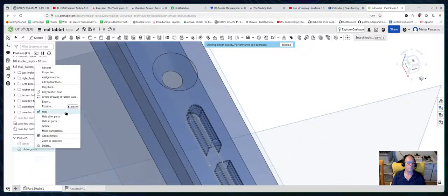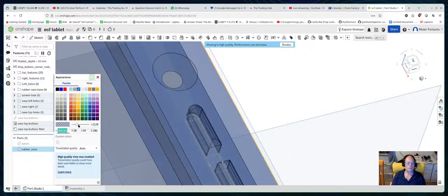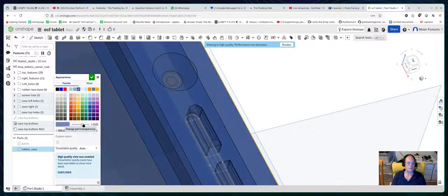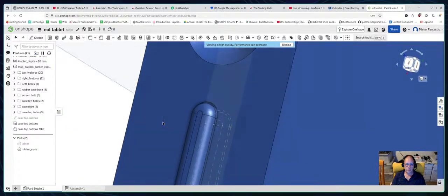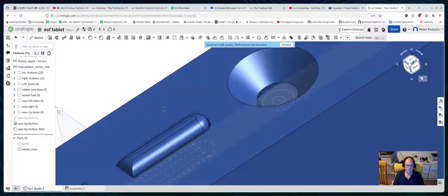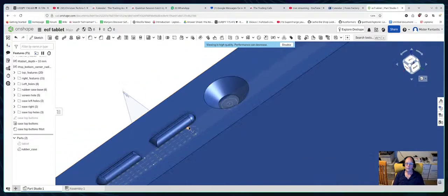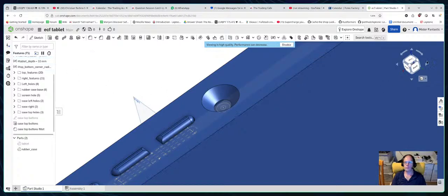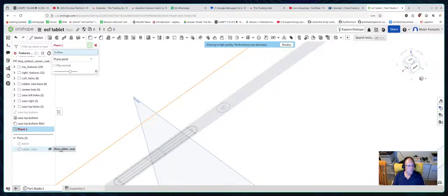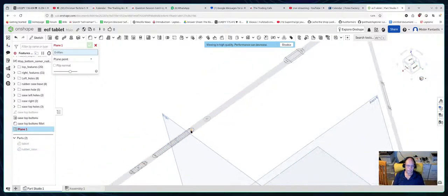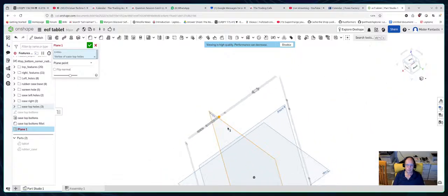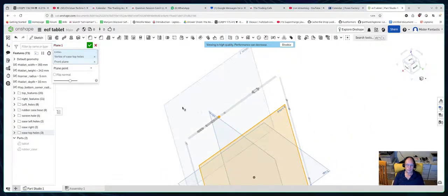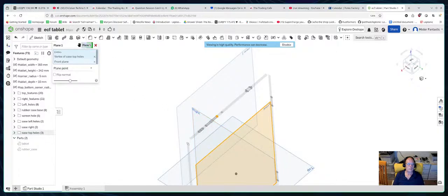Let's make this not so transparent now. So they've got a 0.2 mil gap, so you can actually press them. Let's do the cross section, create a new plane. It's going to be a point plane, so that's still going to be the point there. And where's the plane? It is the front. We'll call it cross section plane.